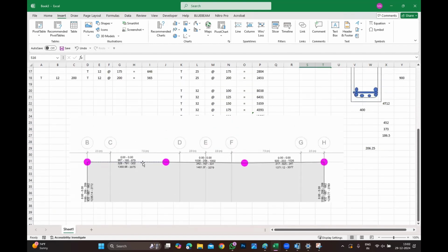Look at the bottom rebar. Bottom rebar: 791, 767, 825. If there is a huge difference, you don't need to follow the maximum. If it is a huge difference, then I can separate it, these two beams together, and the last beam in a different diameter. Does not matter.